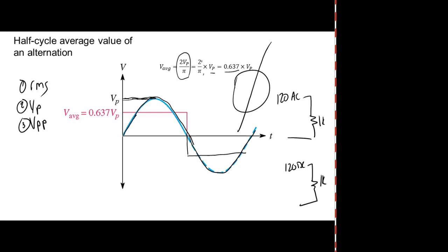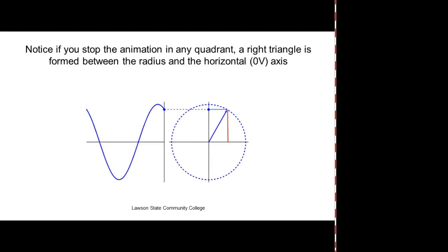So how did the sine wave get its name? Well, a sine wave is generated on a circle, and a circle is equal to how many degrees? 360 degrees. So what we've done is we've adopted that over to the sine wave, but we don't call it rotational degrees, we call it electrical degrees.